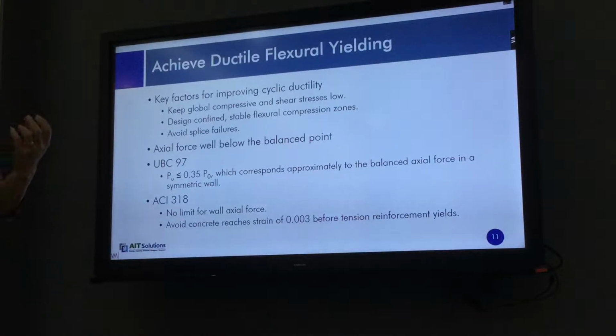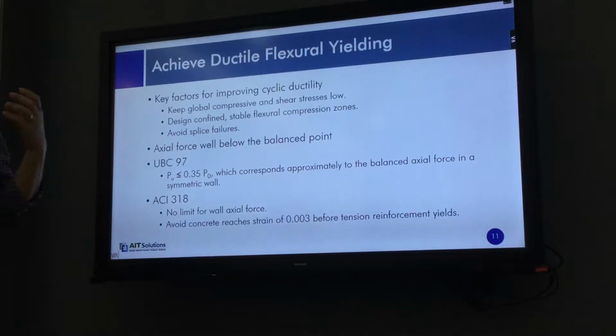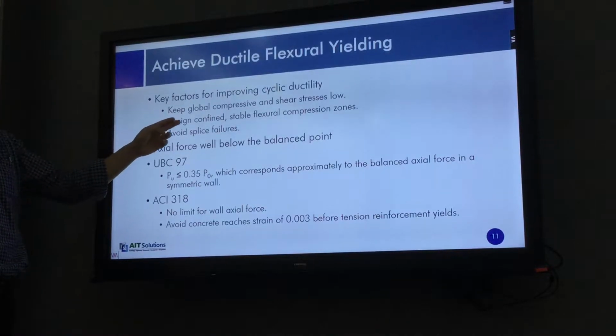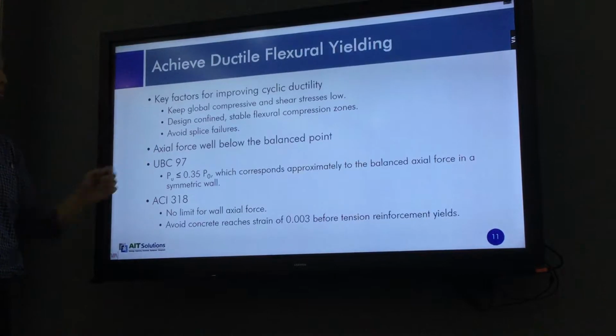To improve the ductility of the wall in the flexure mode, we have to design the wall with low compressive stresses and shear stresses. Although you provide good confinement, if your shear demand or compressive demand in the wall is large, the ductility will be reduced. And we also have to avoid splice failure.